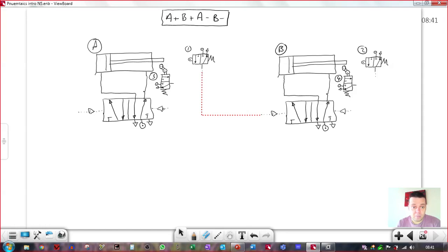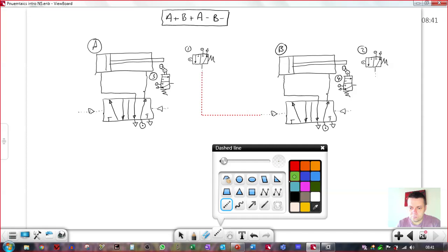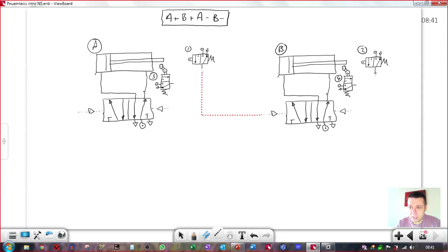So this guy must in-stroke valve A. Let's pick a different colour. This guy must in-stroke this guy. Nice one. So now we've got A in-stroke, and when A in-strokes, it'll actuate valve 3. And the next thing that happens is that B instrokes, so valve 3 must in-stroke, so valve 3's got to go all the way over to here, right?